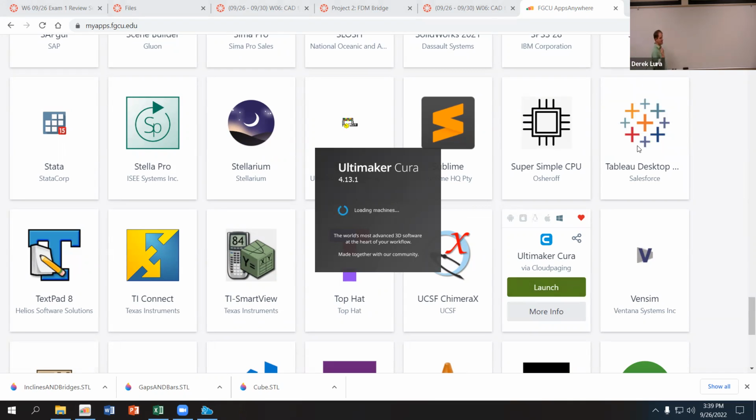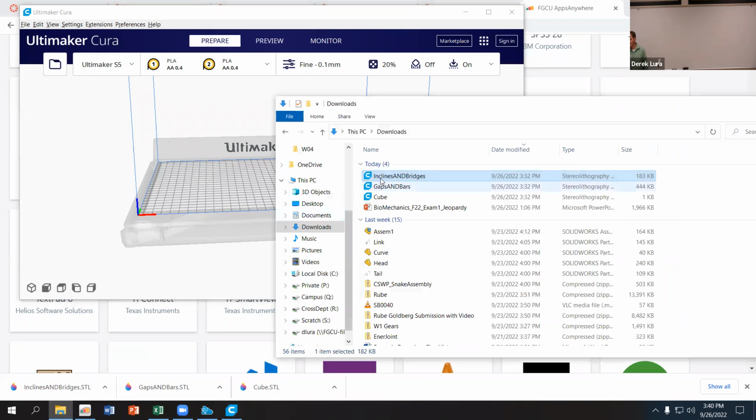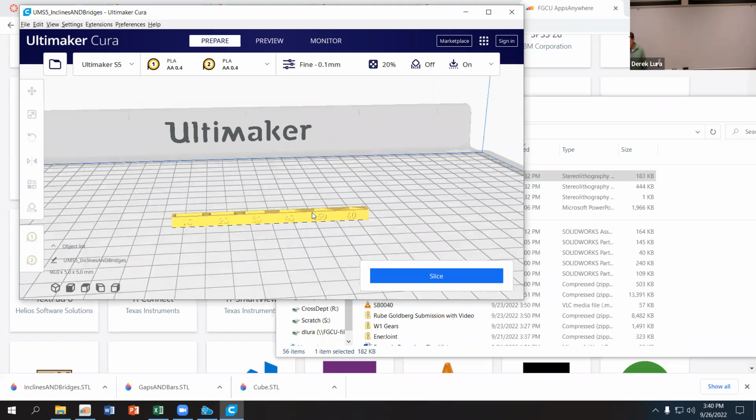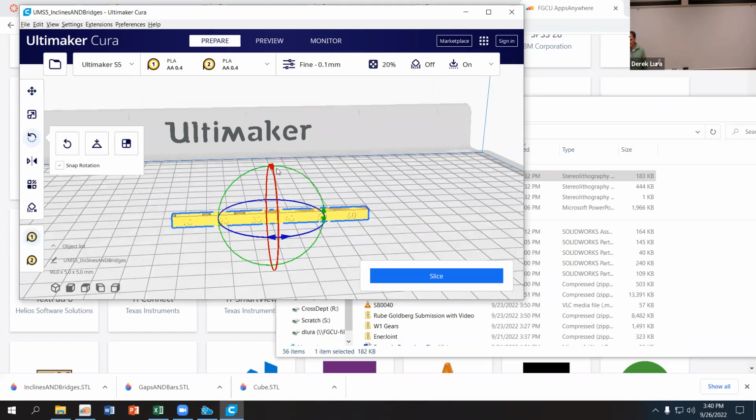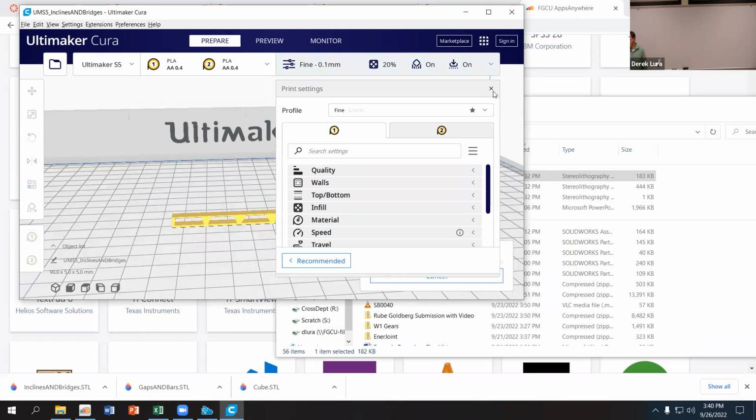So with that support option checked, for all of those faces where the incline was past whatever threshold is set inside the system, it generated material below that surface to support it. And so you get a better quality print. And then on this one that I have the physical part, I just told it not to do that. So you could see what the quality looks like without the supports at those angles. I forgot to turn the supports back on. I work fast because it's going to crash on me again.